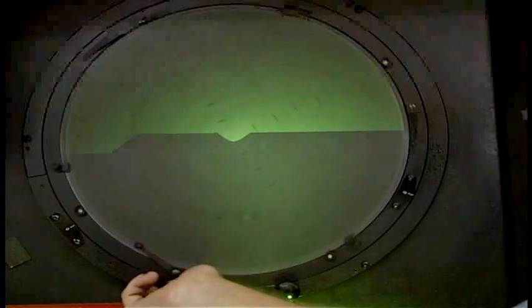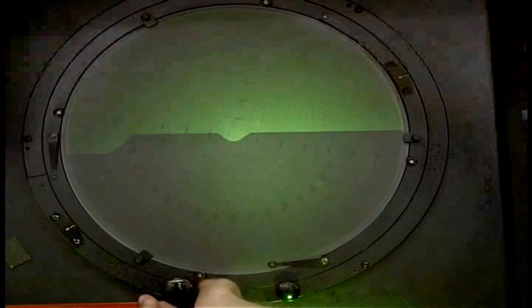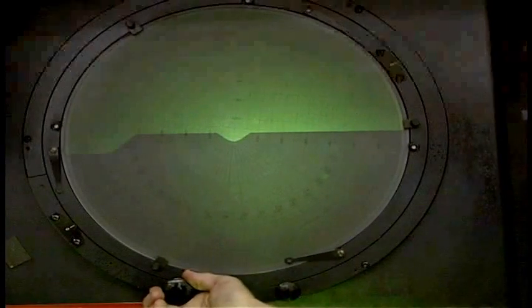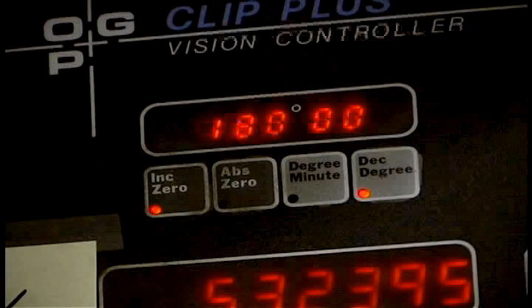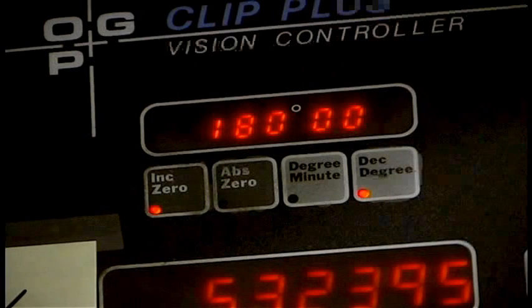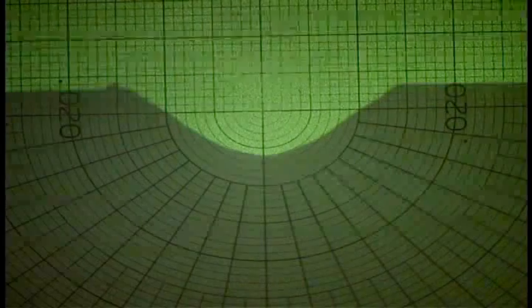The radius of the groove can also be checked on the chart. Rotate the chart to 180 degrees to place the arcs on the bottom of the chart. Check the digital display to be sure that the chart is at 180 degrees. Place the shadow of the arc over the line which most closely matches the arc on the chart. Since the magnification is at 50 times, each line equals 1/1000th. Therefore, the radius of this arc is 8/1000.